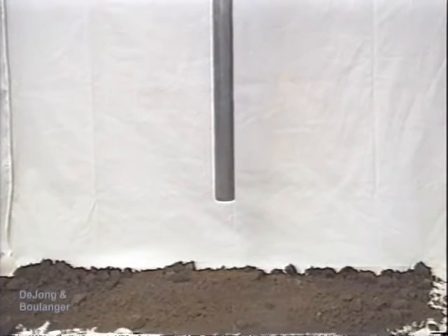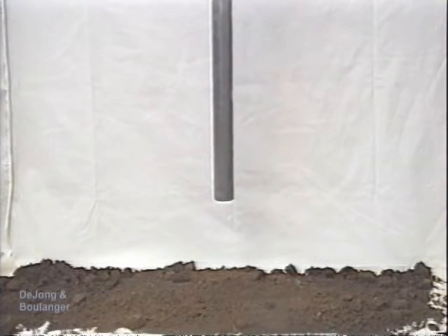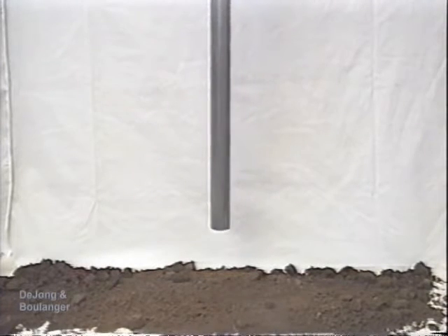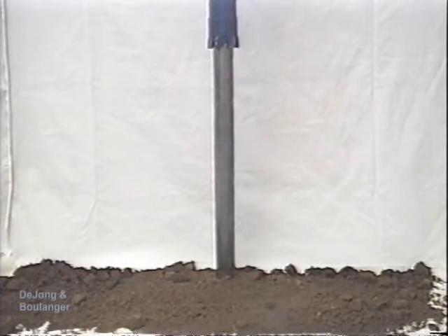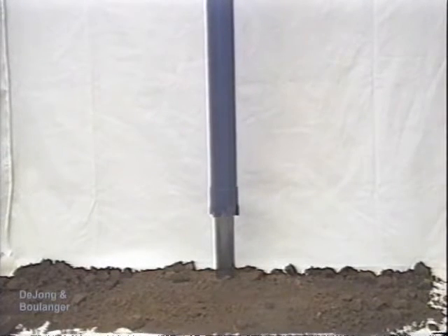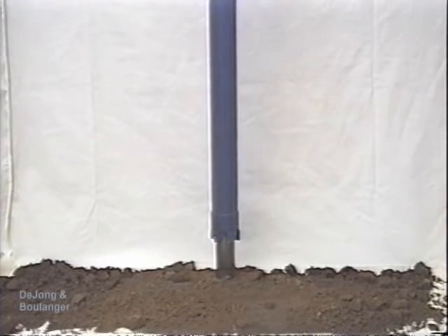While the pitcher sampler is being lowered into the hole, the thin-walled tube is suspended from the cutter barrel, and drilling fluid circulates downward through the tube and flushes the cuttings from the bottom of the hole. When the tube encounters the bottom of the hole, it is pushed upward into the cutter barrel, while the circulation is diverted outside the tube into the annular space between the tube and the rotating cutter barrel.